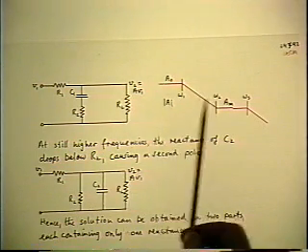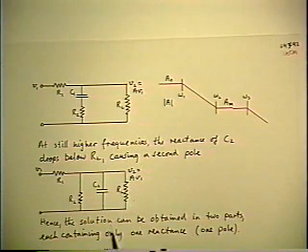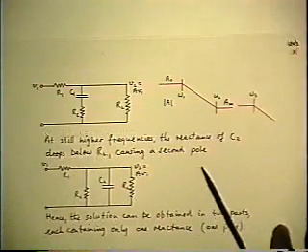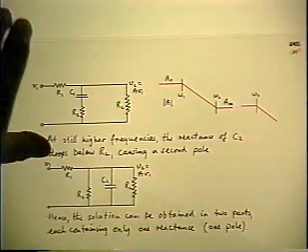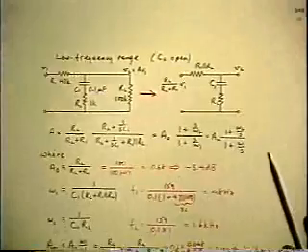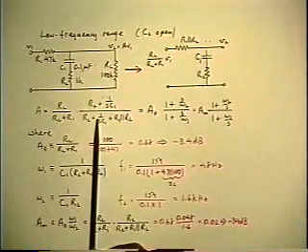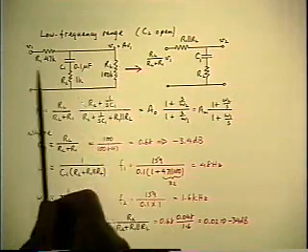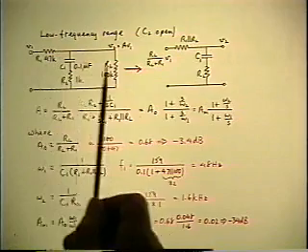And the approximation of dividing the result into two frequency ranges is equivalent to making the approximation that the two real roots of the quadratic are well separated. It's the same approximation. So the solution finally can be written by solving the two pieces separately. This part of it is the same lag-lead network we talked about before after you make the Thevenin reduction.